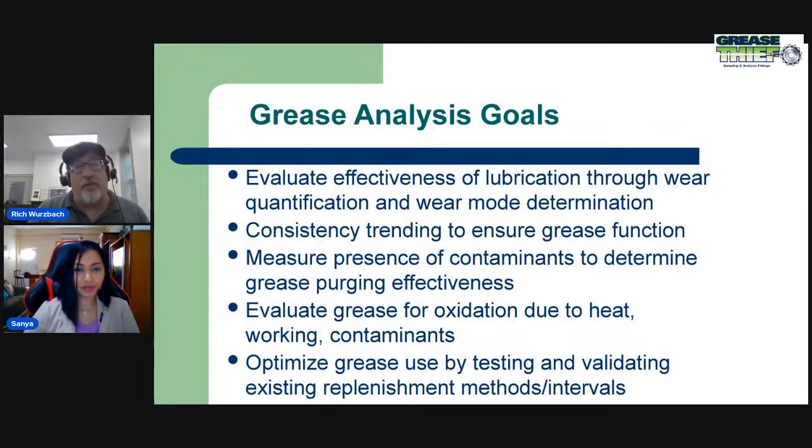So what we can do now with analysis is we can say, is it effective? Is our current practice that we have set up for the amount and the frequency of replenishment keeping the dirt away? And you'll see it in the grease. You'll see the particles. You'll measure the moisture levels. If it's not adequate, we increase it until we get that taking place. And by doing so, we're going to extend the life of our equipment.